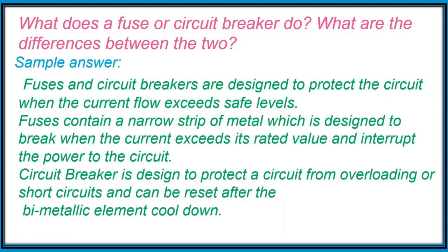What does a fuse or circuit breaker do? What is the difference between the two? Sample answer. Fuses and circuit breakers are designed to protect the circuit when the current flow exceeds safe levels. Fuses contain a narrow strip of metal which is designed to break when the current exceeds its rated value and interrupt the power to the circuit.